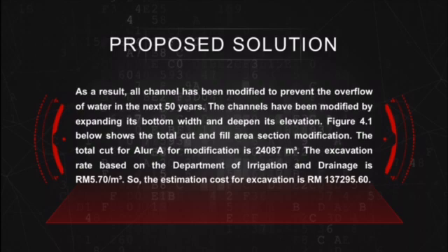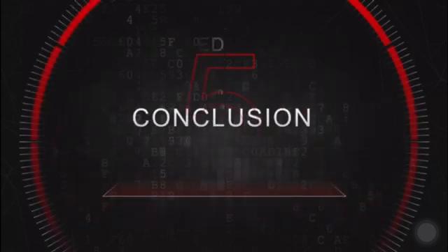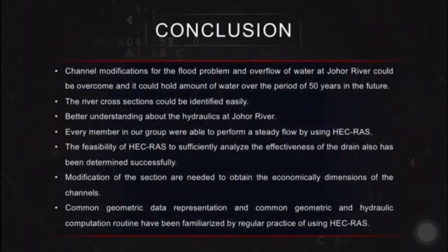The total cut for all channels for modification is 24,087 meter cube. The excavation rate based on the Department of Irrigation and Drainage is 5 ringgit and 70 cents per meter cube. So the estimated cost for this excavation is 137,295.60 ringgit.